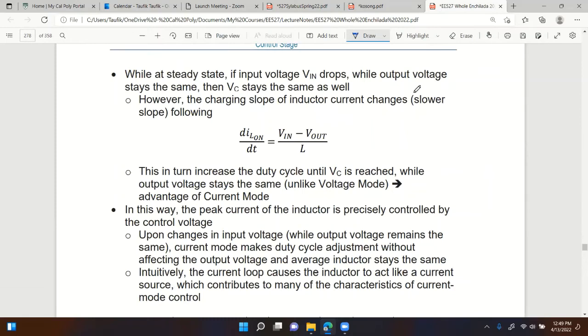All right. Now, that's what happened with voltage mode as well, so there's no difference there. It's a different mechanism for compensating for the drop in the output voltage, but they are both doing the same thing. They are both fast in responding to a change in the output voltage. But what about when the change is in the input voltage? Remember, this is the disadvantage of voltage mode. How could current mode control improve it? Well, let's check this out.